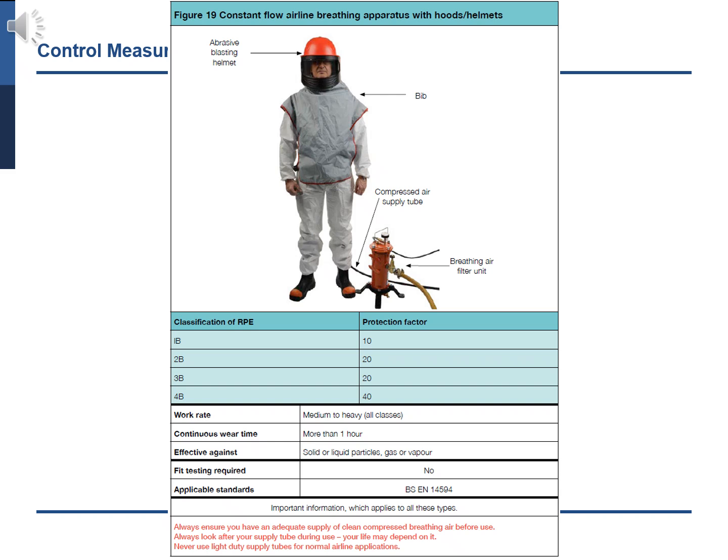Continuous wear time, recommended for more than 1 hour. Effectiveness, effective against solid or liquid particles, gas, or vapors. Fit testing, not required. Standards, complies with BSEN 14594. Important note, ensure you have an adequate supply of clean compressed breathing air before use. Always look after your supply hose, as blocked hoses may lead to suffocation.